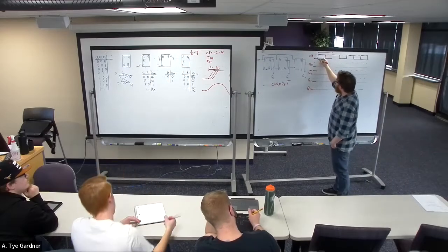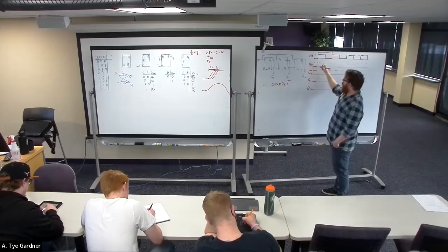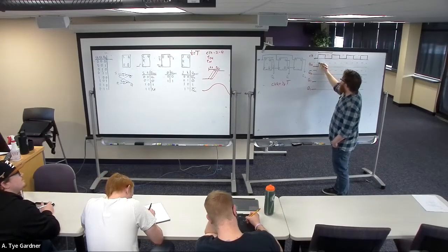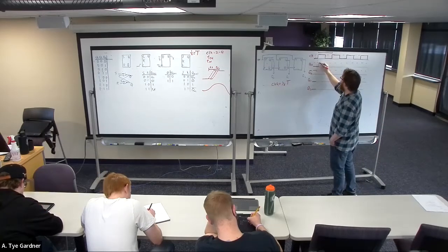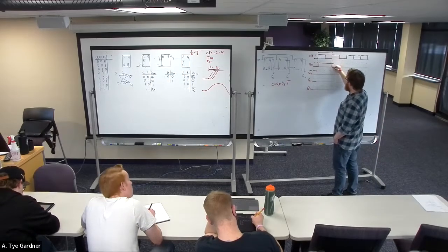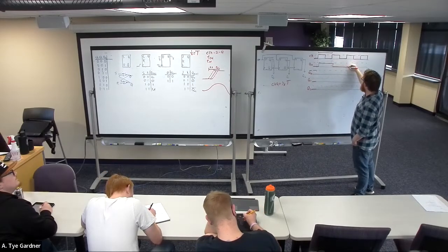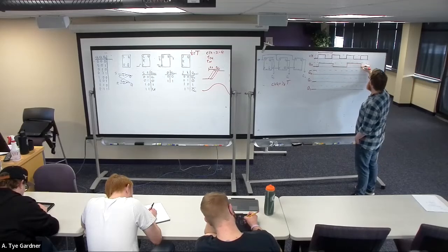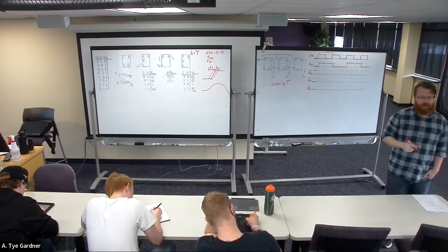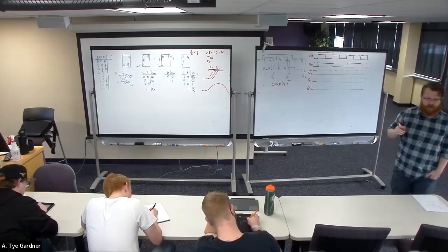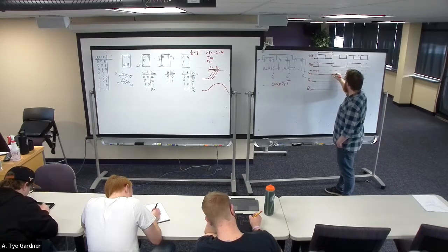Okay, so this rising edge happens. The Q0 is enabled, right? I said the enable is on. So after a little bit of time, it steps up. Comes over here, next rising edge, a little bit of delay, it toggles, little bit of delay, it toggles, little delay, it toggles. Well, the Q bar in this case, Q0 bar, is the same thing. We're going to assume same delay, which is a pretty reasonable assumption. It's just the opposite.